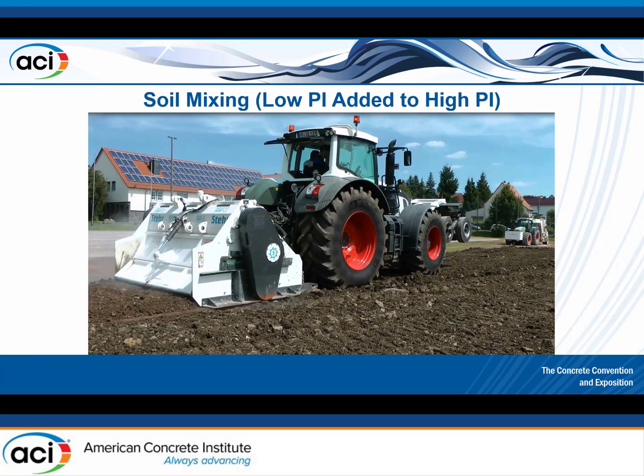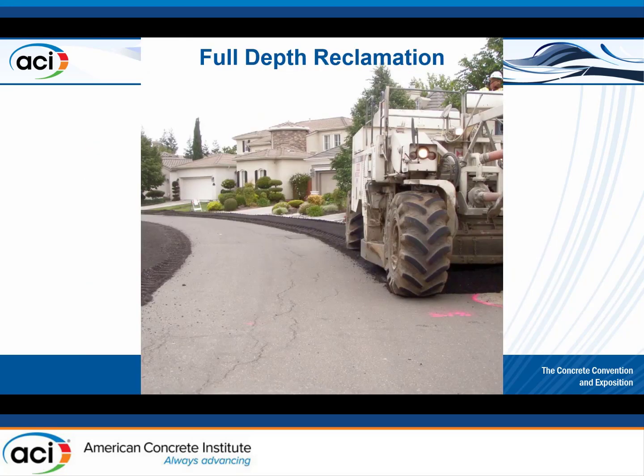And then we can do soil mixing, where we just bring in a lower PI soil and mix it in with the high PI soil. Or again, remove and replace. So there's a lot of different things that you can do to mitigate some of those problems.